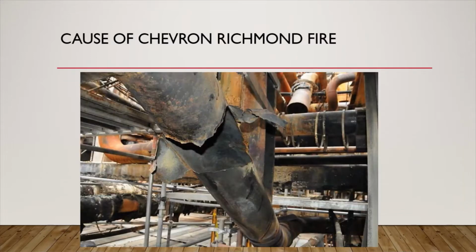Officials had seen the corrosion in the piping but had no plan to replace it, as they deemed the section of piping good enough to last up to 5 years longer until the date of the next turnaround. The pipe was more corroded than they thought it was, and it led to a leak that burst the pipe, which caused the explosion. The cause of this was corrosion under insulation, or more commonly referred to as CUI, which is the most common damage mechanism in the oil and gas industry.